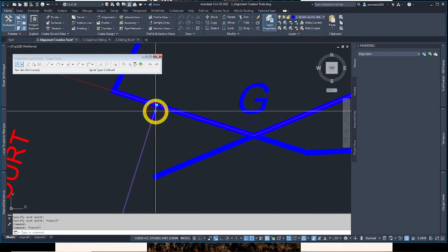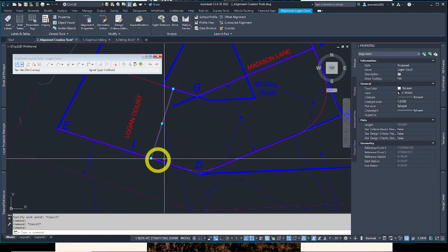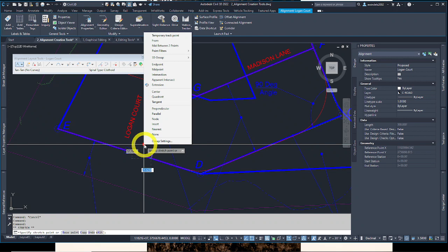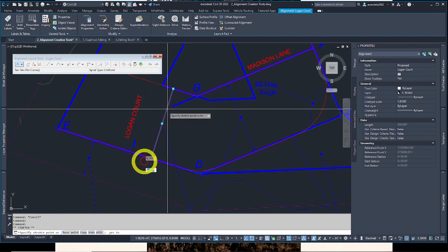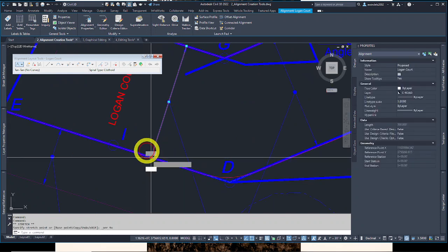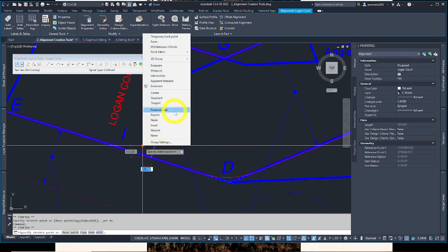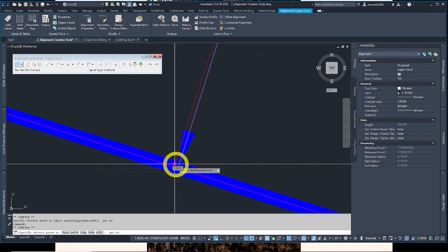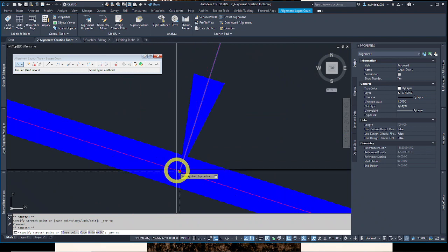You can totally regrip this. It only has, it's a straight shot. You can move it around, and I'm Shift plus right click. You can get your one-time O-snaps. And I verified it was perpendicular. You see what I did. I'll shift and right click, or you can turn it on here and you're running O-snaps. It'll stay on though. Hit perpendicular. I'm going to zoom way in. Sometimes I get this symbol. It says perpendicular. That is the perpendicular symbol there.